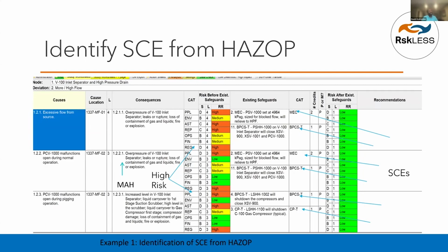So one of the best techniques you can use to identify what is safety critical is actually the HAZOP. And that's why when we do HAZOP, we always talk about what excellent looks like. When you want to employ people to do risk analysis for you, you have to employ a competent facilitator, or sometimes a competent scribe, able to document what your risk actually is.